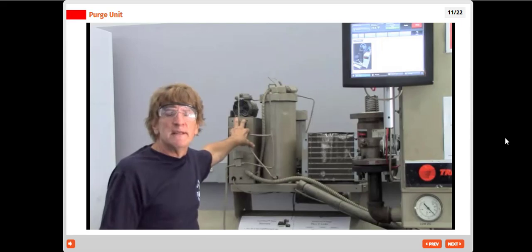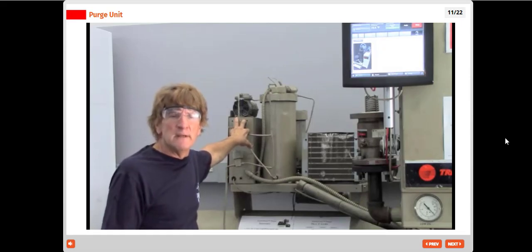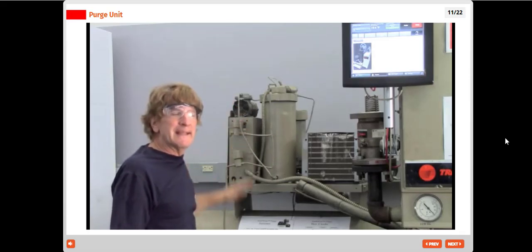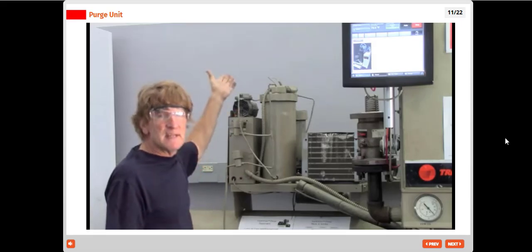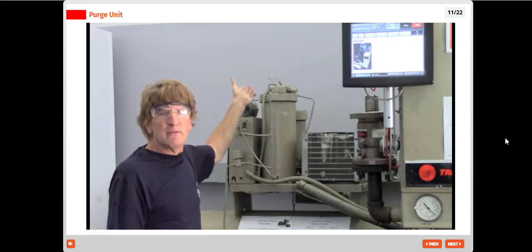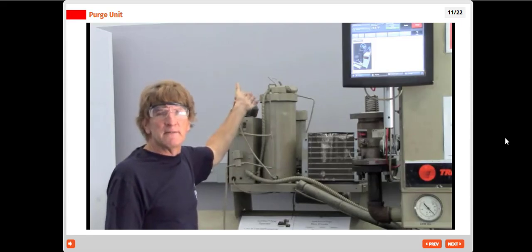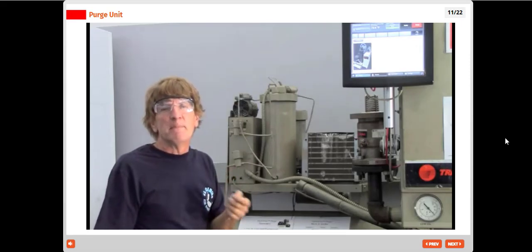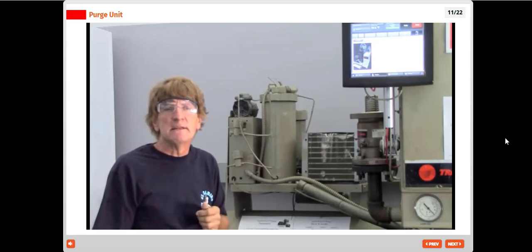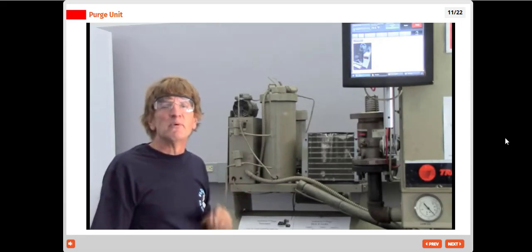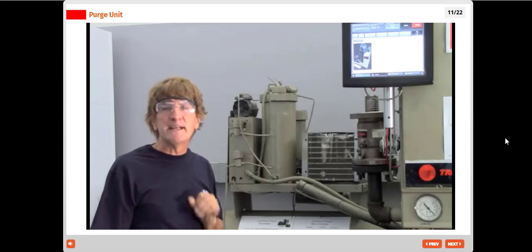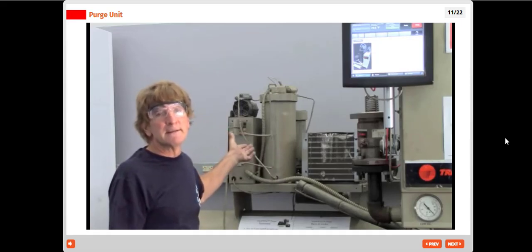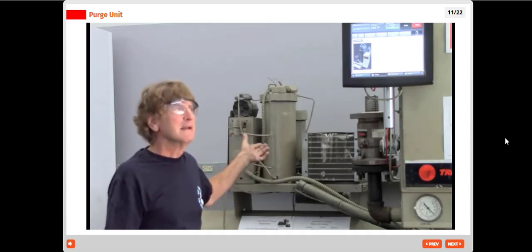It's a refrigeration unit that takes the air and refrigerant samples off the condenser, normally, condenses the refrigerant, puts it back into the evaporator, and relieves the non-condensables either into a regenerative container so we can clean it out some more, or vents it out into atmosphere because it is not a refrigerant, it is non-condensables. Does a great job of removing those non-condensables. So one way we look for leaks on a low-pressure machine is looking at what our purge rate is. How many times an hour or a day I'm actually purging.